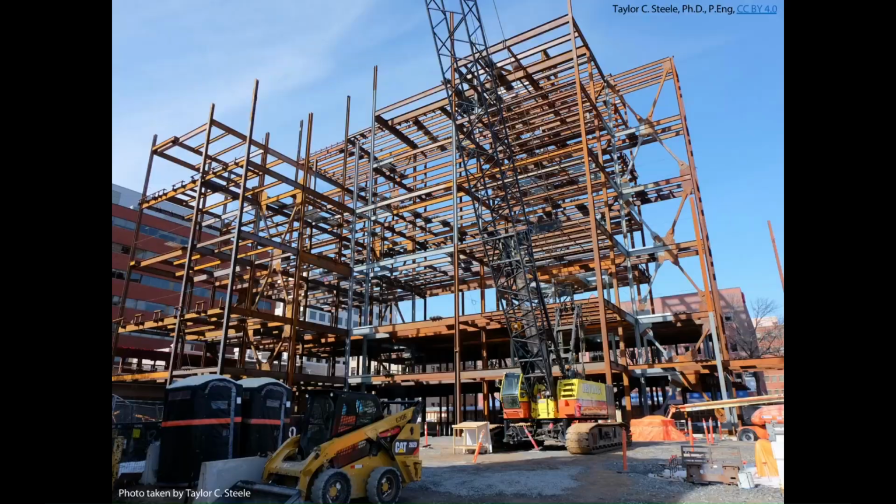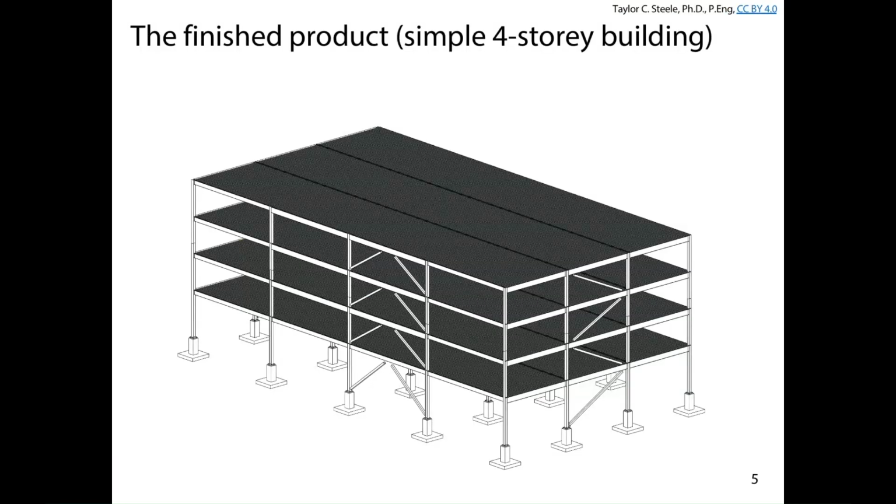In general, this is what somebody like Ocean Steel or Tech Steel or York Steel or other provinces' steel fabricators would be responsible for. Basically everything above the foundations at the top of the grade level on the site to the finished floor level where we have, for example, some steel decking put down on top of the joists. Everything from the top of the foundations to the underside of the concrete floor is something that goes into the steel contract, and that's what the structural engineer would be responsible for designing.